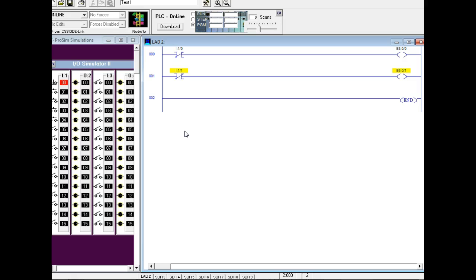Okay, so that means if it's examine open, that's true. So that means this normally closed contact would be true. Understand? Because I'm getting a 0 back, so I get a 0 back, that makes it true. Now the top one, we got that set up for examine open, but you got a normally closed switch. So that is what? False. So that means this one's not picked up, since that's false.